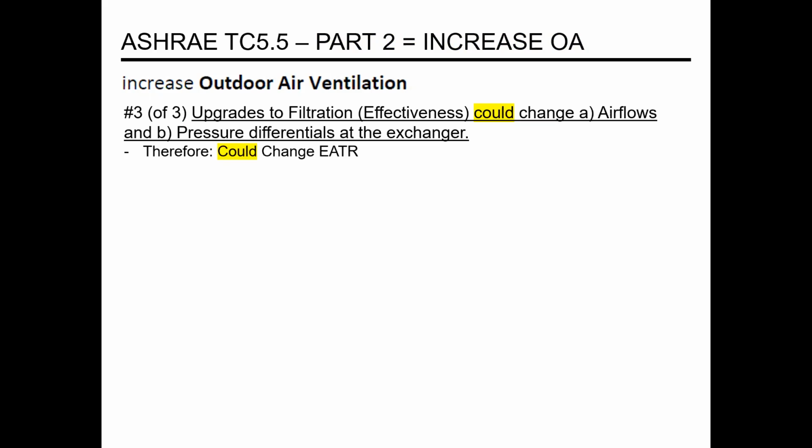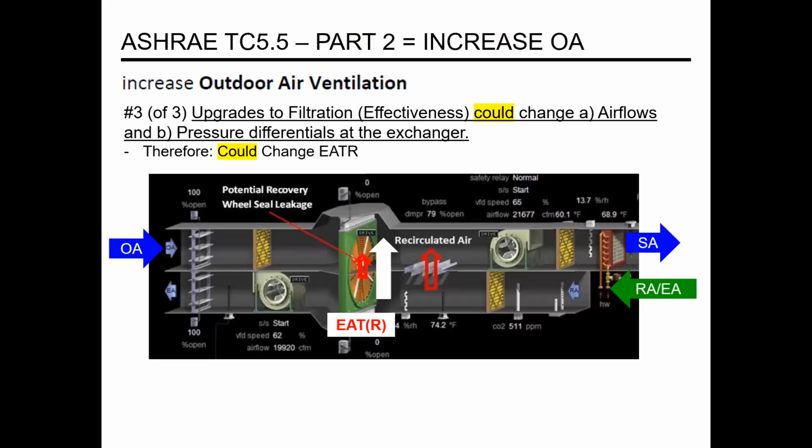Number 3, maybe it's not so associated with outside air ventilation, but if you do upgrade your filtration or your effectiveness, you could change your airflows, and therefore you could change your differentials, which could change your exhaust air transfer ratio.